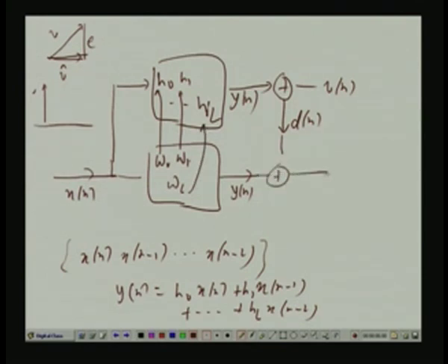So, since the optimal filter is not computed directly, it is computed in an adaptive way. So, you put it in the adaptive filter framework, this is Dn, this is Yn, this is En, and use this En in the LMS mode to adapt them. So, finally, after convergence, W0 should approach H0, W1 should approach H1, WL should approach HL, and so on and so forth.